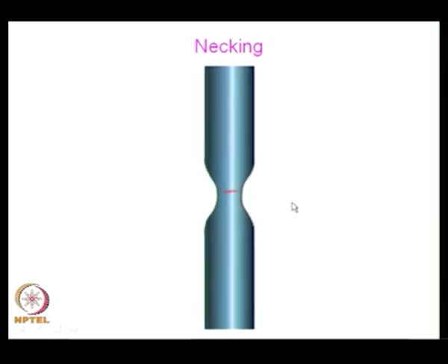and after some time you find suddenly on the ends you have a shear failure at 45 degrees. So, the material separation starts from the center of the specimen and proceeds outward, and you have a shear lip on either side. You would see the animation in full. So, this gives a plausible explanation of how necking could be viewed.